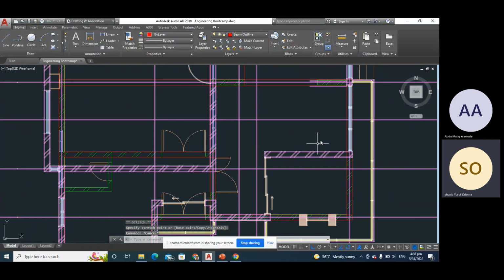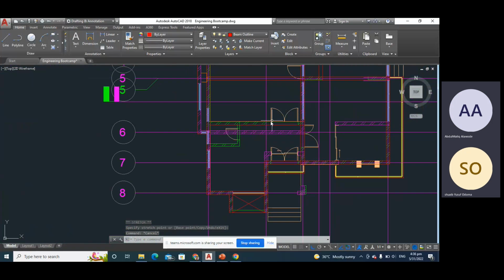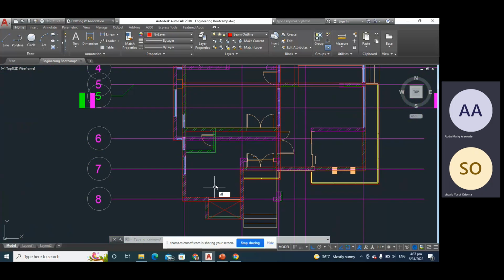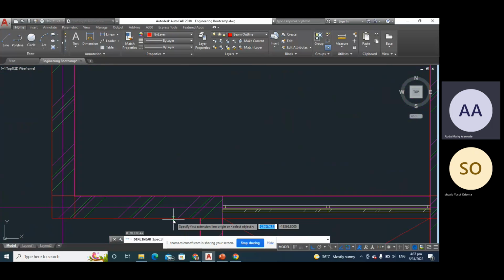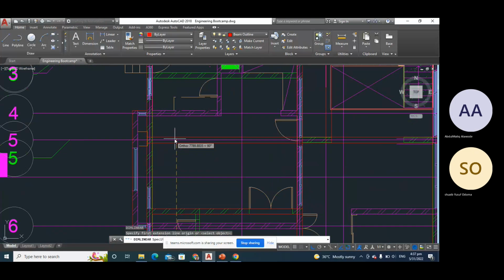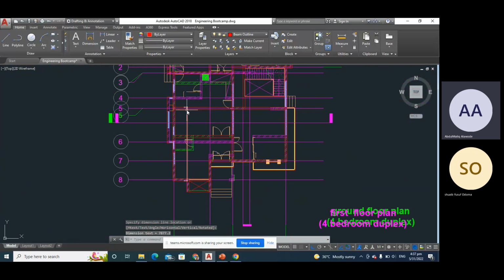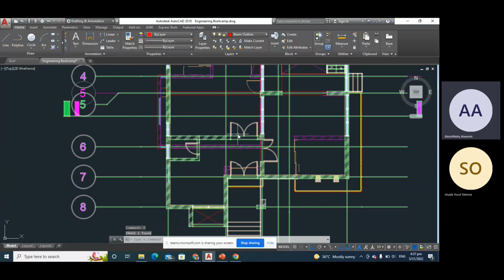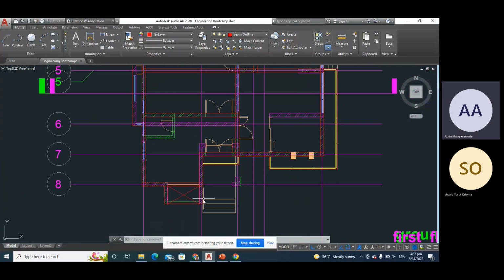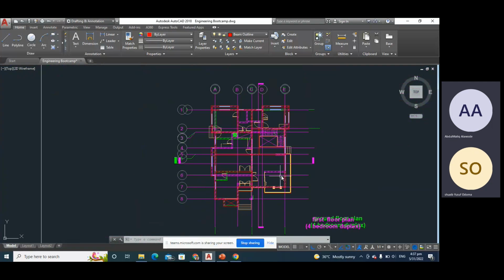Okay. Do we need this beam here also? Yes, we need it, because if you take it from here to here, by the time you delete it, we are going to have the effective span from here to here to be 7 point something meters, which is too long. So we can't do away with this beam. We have to leave it like this. So is there any other thing that is left for us to do? I don't think there is any.